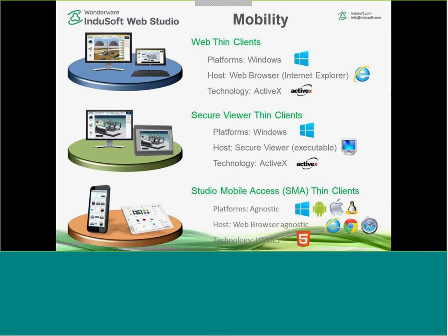IoT View. And a thin client is a remote station where you can access the graphical interface, read data, interact with the application, change set points, send commands. So operate the application the same way you would on the local station. But doing that from a remote station where you do not have to install the product, the application, and the license. So over the years, we designed different types of thin clients.